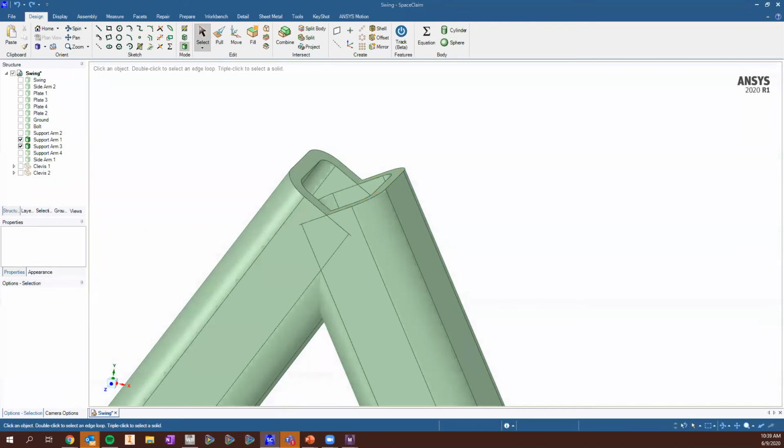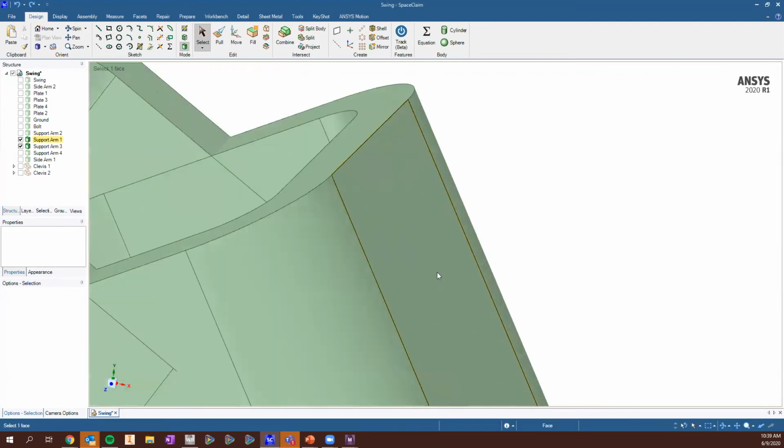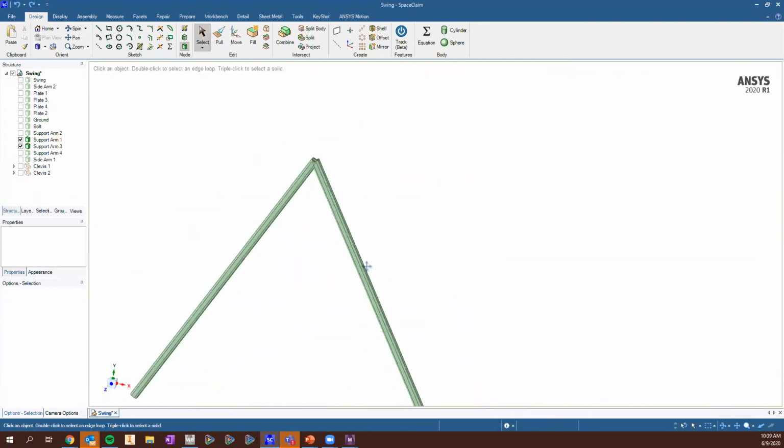Is there a general rule of thumb of thickness where using shell elements is no longer valid? That is a good question. Ansys has two different types of shell elements, one for thick and one for thin shells. The limitation depends on an equation I don't have in front of me, but it relates thickness to the length and your volume.